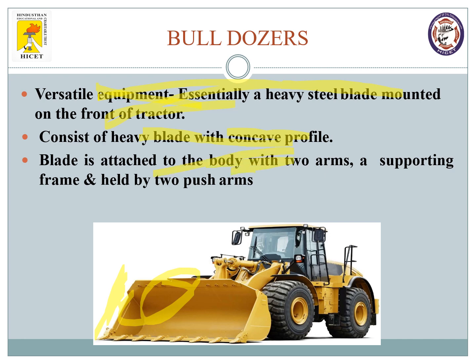These bulldozers are generally used to push very strong earthwork. If you are going to dig, you can dig, or if you are going to transfer, you can transfer. You can move from one place to another. It can transfer a low volume at a time, but its capacity to move material is very high. So bulldozers are primarily used in this type of construction. In your highway, if you are going for an alignment survey, and once your alignment survey is over, if you need to transfer materials, or for cutting and filling purposes in highways and railways, bulldozers can be used.